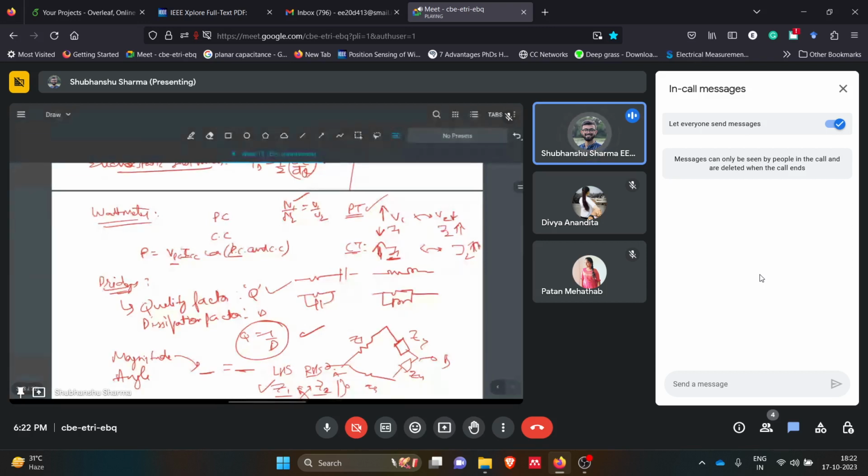So in the concept of resolution, and then in this dual slope conversion of analog to digital, those equations, like the input, the integration time and the deintegration time of that dual slope converter, that equation you should keep in mind.